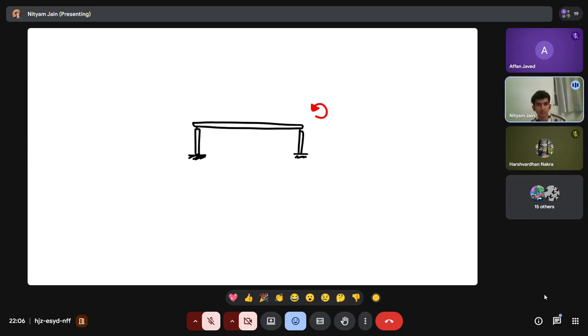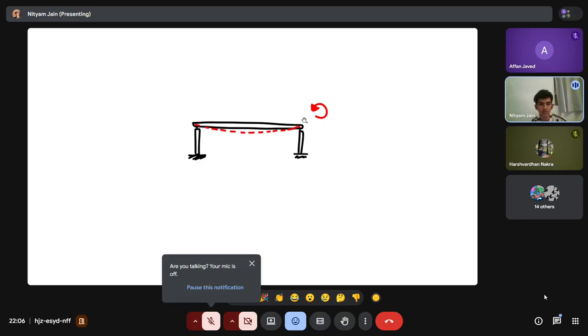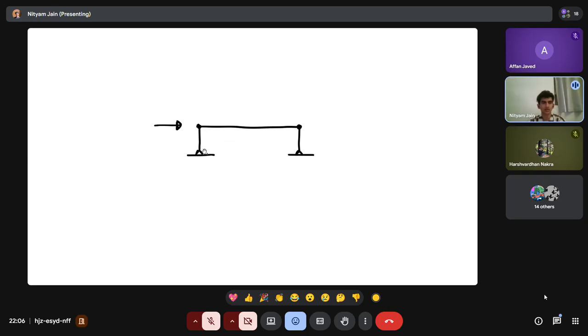And if we take a simply supported beam or pin joints here, then the deformation can be sort of like this. If in a structure you have two pin joints and two hinge joints, that is the limit of any structure. There cannot be more than three pin joints, and I'm just generalizing hinge as pins here. So if lateral forces come, the rectangle will just turn into a parallelogram. So that is one of the concepts: the collapse mechanism of any structure is three pins.